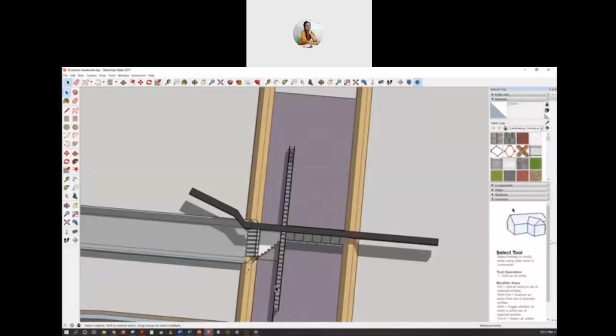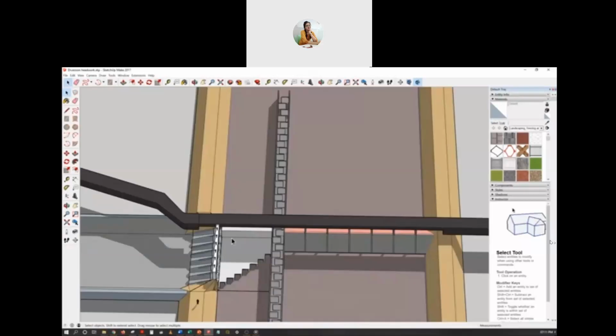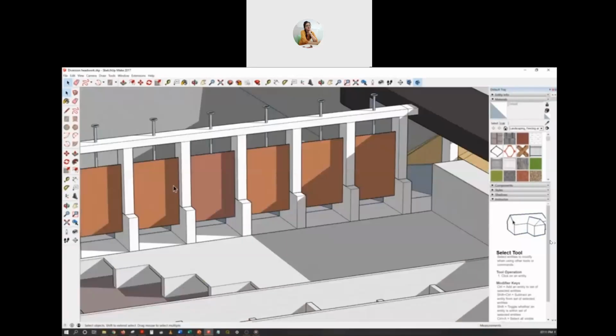Now, the off-taking canal is fed by this kind of work, which is called a head regulator. So a head regulator is provided with these kinds of gates. So these are the gates. Mostly these are made of metal and they are raised or lowered based on need. Here I have only shown this kind of steering or screw thread arrangement. If you rotate this, it will be either lowered or raised.